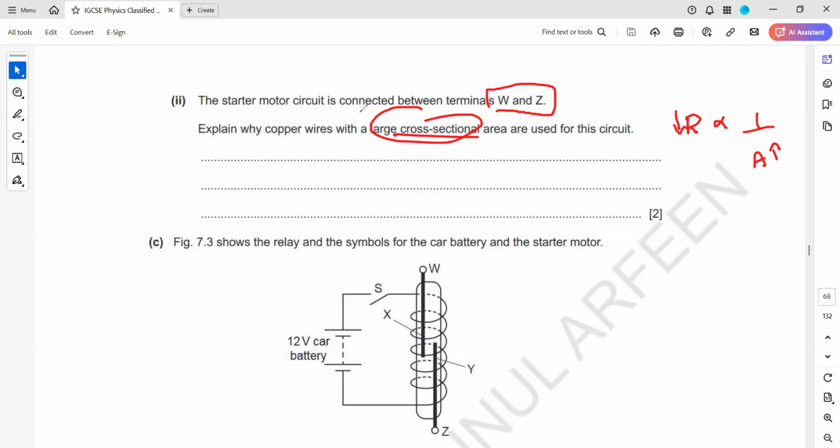The charger current is in amperes, for example 0.3, 0.7, very low. Is the HDMI cable so thick then? Yes, sir. No, because the HDMI cable is carrying information, data, transferring a greater amount of data in a short time. That's why it is using a large cross-sectional area. It's not about the current.